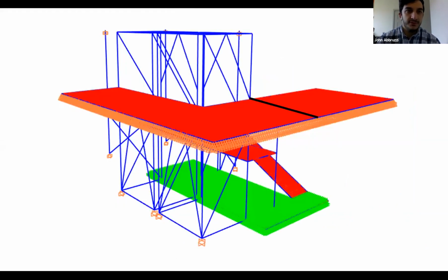Again, this is a wire mesh view of the no platform design. Just like with the platform design, the joint restraints are highlighted in orange and in green. The floor on the left side of the black line is surrounded by walls, while the floor on the right side of the black line is open to a main area, making the joints fixed connections. Springs are used and located in the same areas as the platform design.